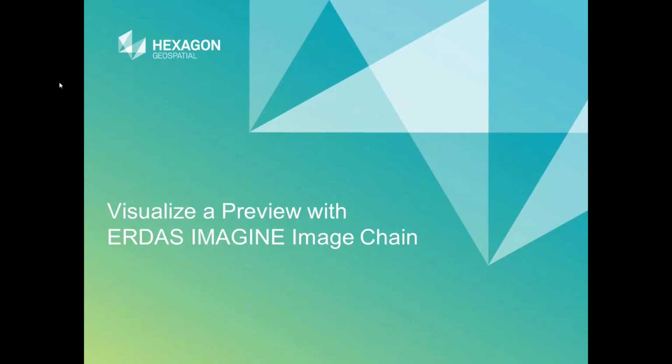Our topic, flexible ways to visualize a preview using the ERDAS IMAGINE Image Chain. In this module, we'll generate an NDVI image preview to see how to use the image chain introduced in ERDAS IMAGINE 2015 to swap display modes from panchromatic to pseudocolor, enabling the preview to be color-coded for easier interpretation.